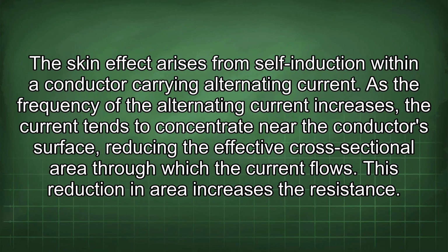The skin effect arises from self-induction within a conductor carrying alternating current. As the frequency of the alternating current increases, the current tends to concentrate near the conductor's surface, reducing the effective cross-sectional area through which the current flows. This reduction in area increases the resistance.